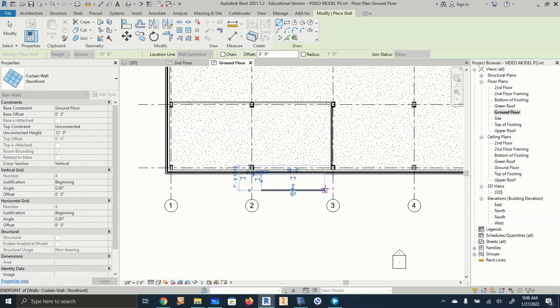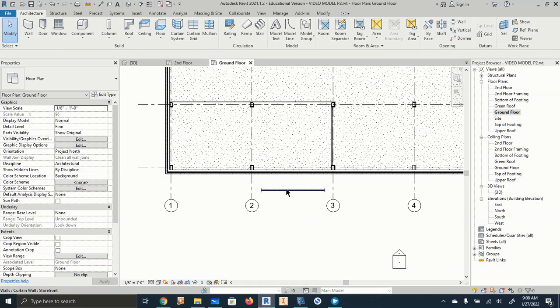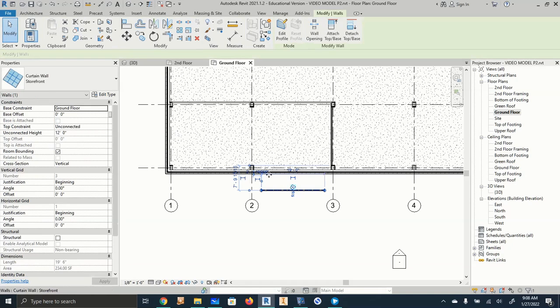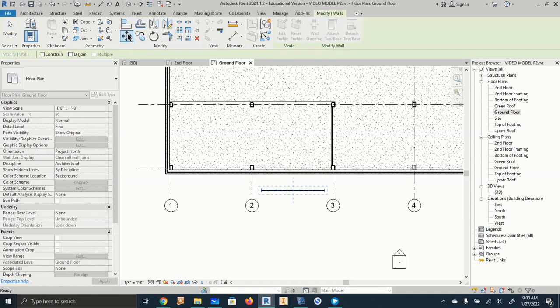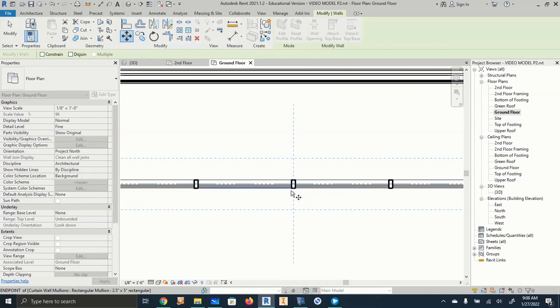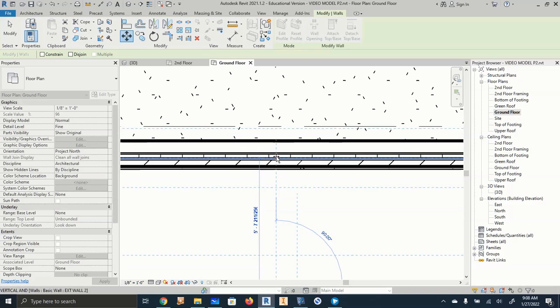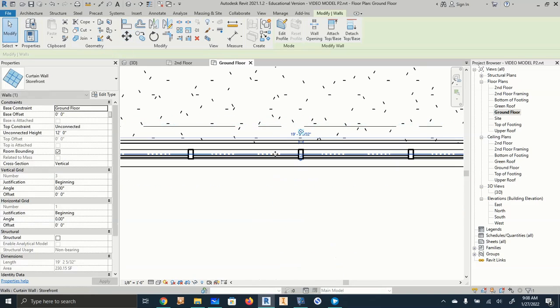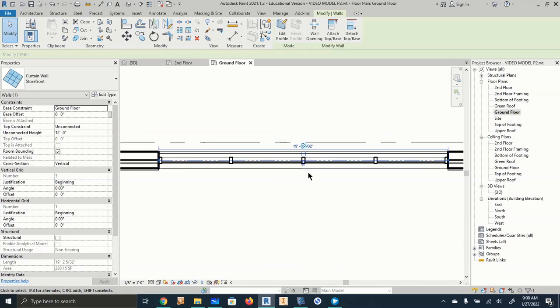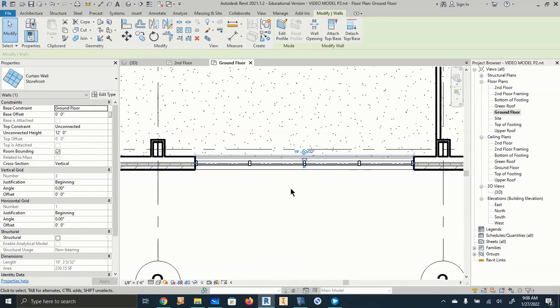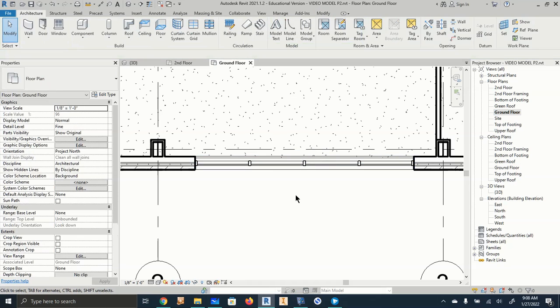All right, so we're going to pick this. I want these arrows to be on the outside, and then press escape a couple of times. Now I'm going to say, I want to move this wall. I click on the wall. I click the move tool. I zoom in on the wall. I'm going to click its center line. I'm going to go to my wall straight above it, and find any center line in here. I'll click like this one. That's going to be fine. Okay? And so it moved it into the wall. That's the easiest way to do those. And we're good to go.